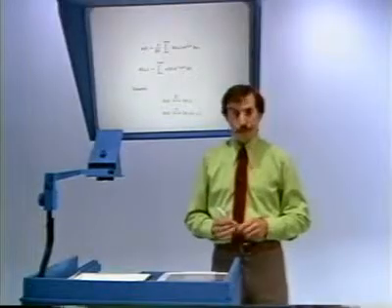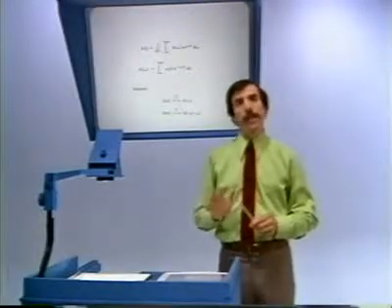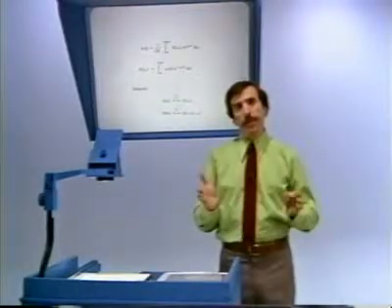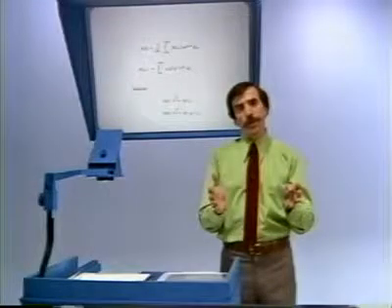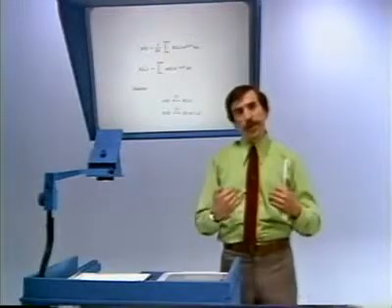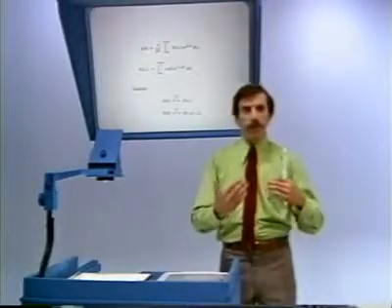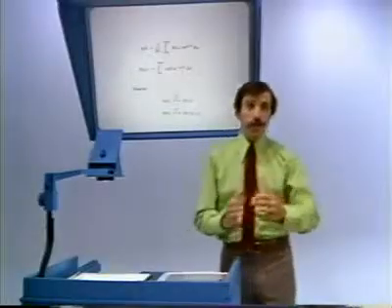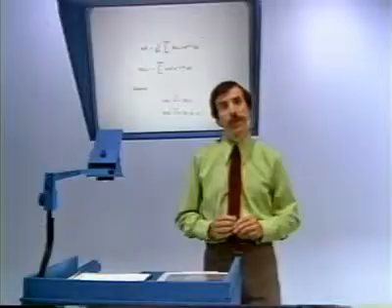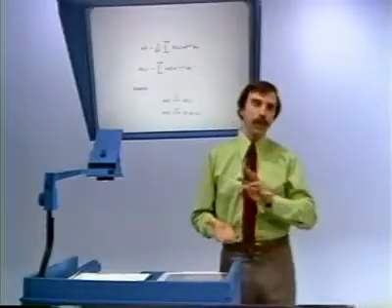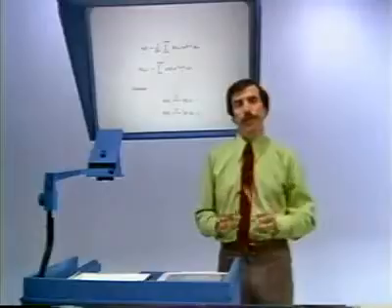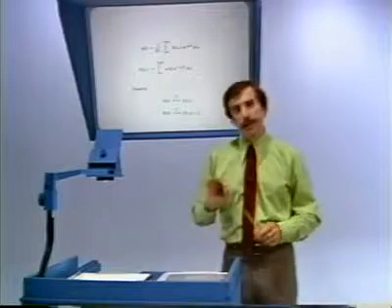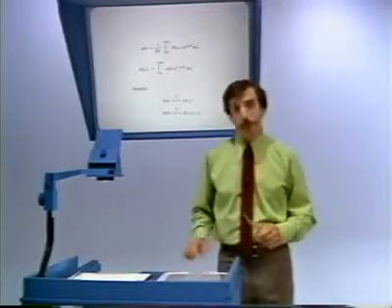It's very useful. It, by the way, is not a duality that surfaced in the Fourier series because, as you recall, the Fourier series begins with a continuous time function and in the frequency domain generates a sequence which would just naturally have problems associated with it if we attempted to interpret a duality. And we'll see also that in the discrete time case, one of the important differences between continuous time and discrete time Fourier transforms is the fact that in continuous time we have duality, in the discrete time Fourier transform we don't.